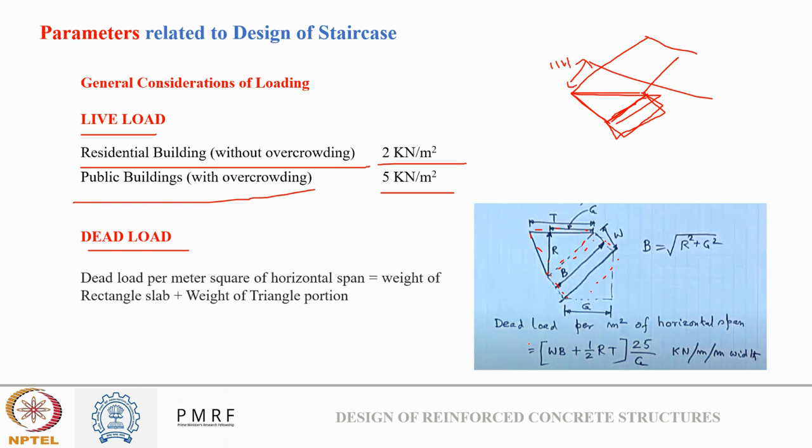Now we can design. So we know the loads, we know the dimensions, so we can calculate what is the moment that is acting. Since it is a slab, if we consider this as a one-way slab, and I know what is the load acting on the slab and what is the dimension of the slab, I can design for reinforcement, the additional reinforcement, and everything.